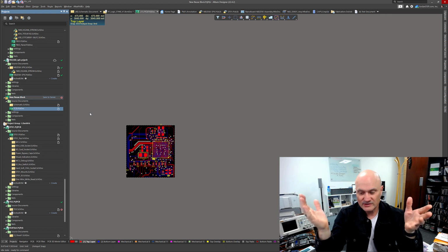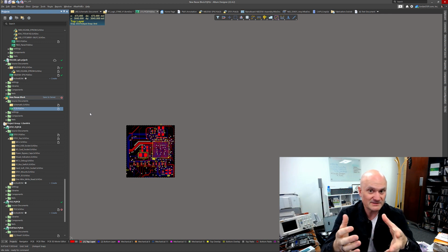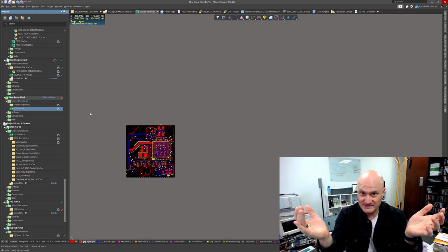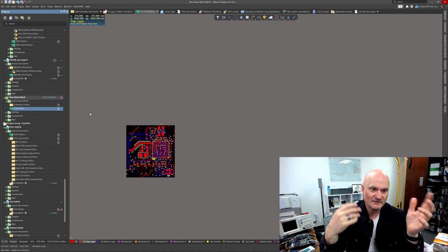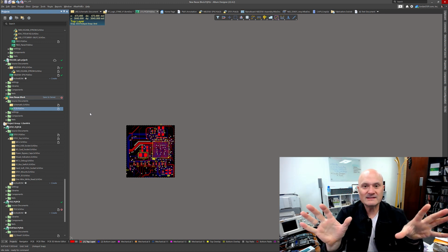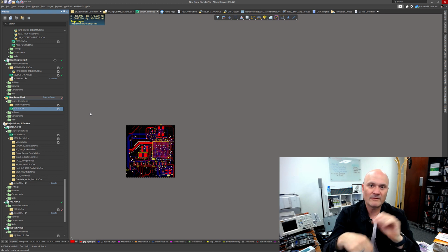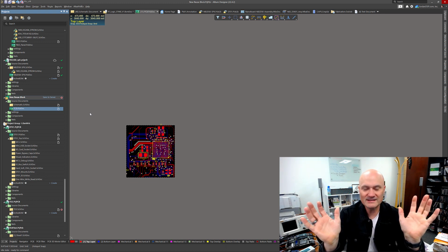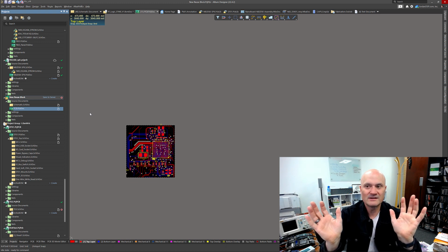For example, you have the Arduino reference designs and you're using Arduinos a lot for prototyping. A lot of engineers are doing that now. And maybe you have an Arduino Zero that's got the SAMD20 microcontroller on it, and it's got everything needed to connect to the microcontroller, program it, do debug. It's got JTAG. It's got all the supporting decoupling and power supply stuff.